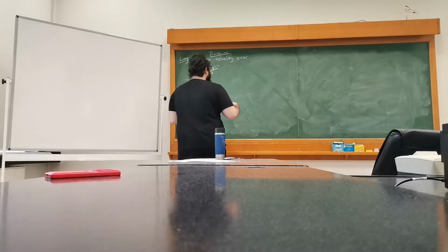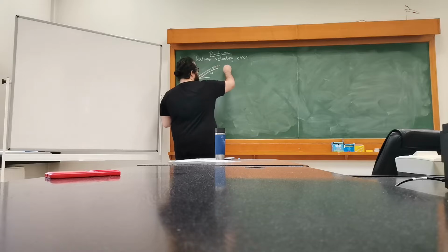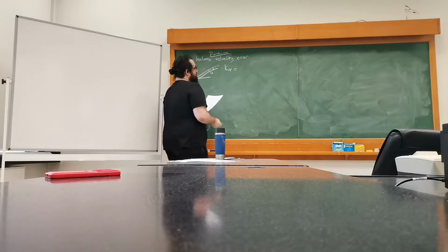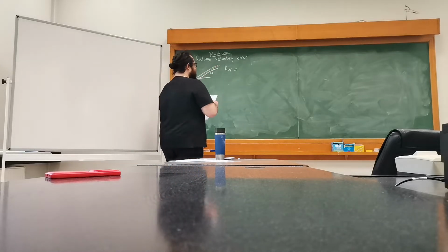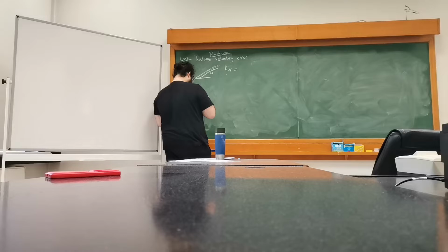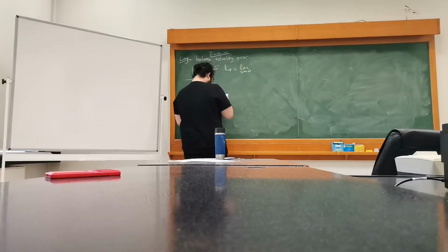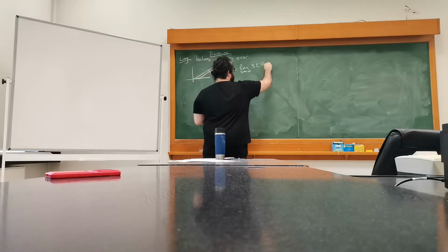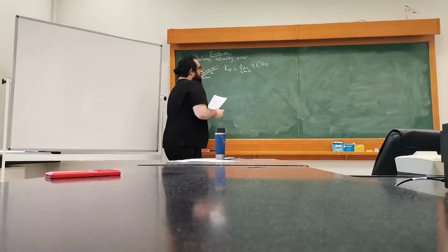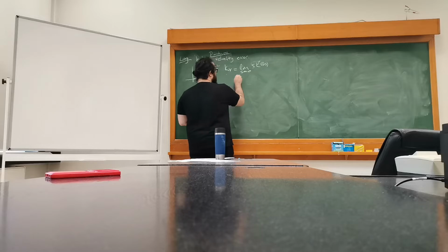Well, in order to evaluate what's really going on or what should really happen, we have to look for the velocity coefficient, which is basically defined in order to examine the velocity error itself. This inverse will give us the velocity error here. And we can do this by using this limit: limit s goes to 0, s times k times G(s). So we have a certain k value, and we know what G(s) is, so basically we can plug that in.